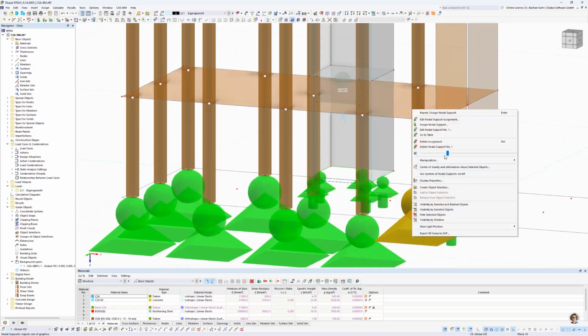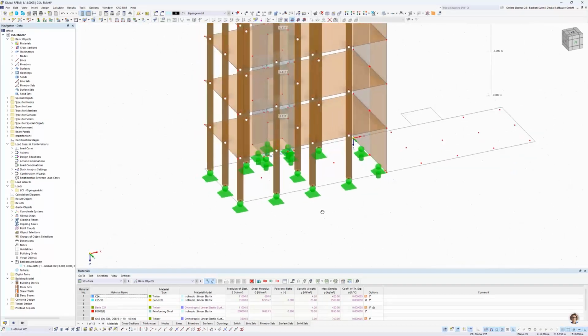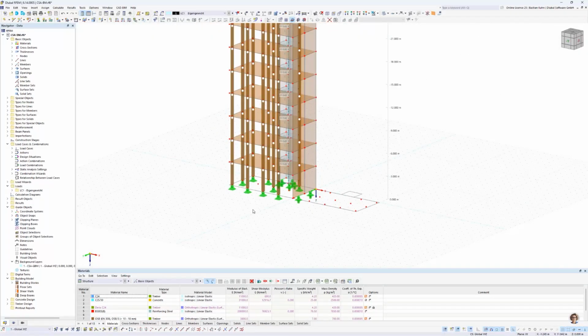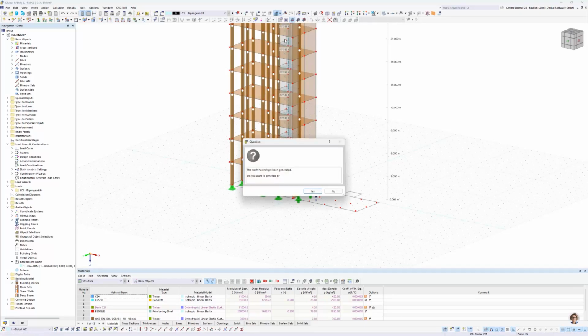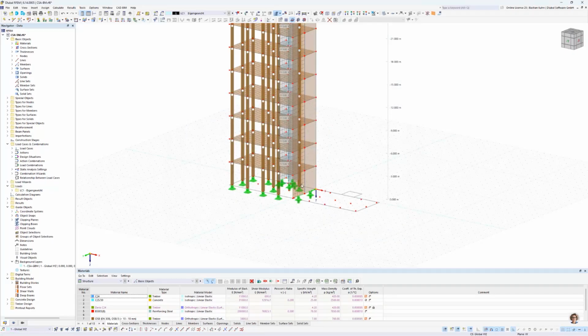Too big. Okay. Good. So centers there. That looks quite good. We can have a little check by displaying the mesh, so we know that everything is modeled correctly before we put the loading on it and also mirror it. So it looks good.